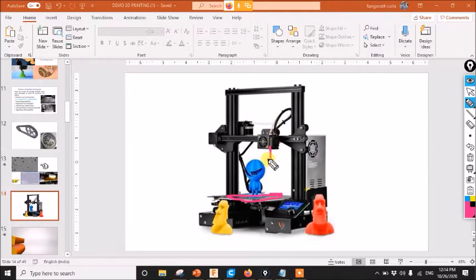The second one is this particular nozzle. These are the two important parameters, or the two areas, where you need to maintain temperature. Temperature is very important in this particular parameter. So once the material is being diffused from this nozzle, when it touches, it needs to get solidified immediately. If it solidifies too immediately, then you will have some cracks on the object.